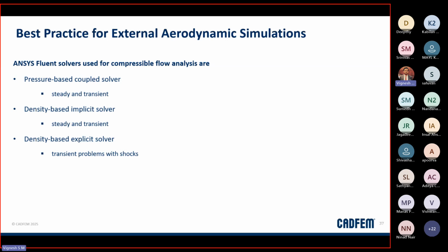I hope most of you are working on incompressible, low speed, subsonic flow. The pressure-based coupled solver is somewhat better to go with, but you can also think about density-based when it comes to high-speed aerodynamics or highly compressible flow for your problem.